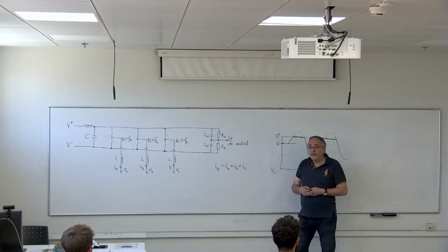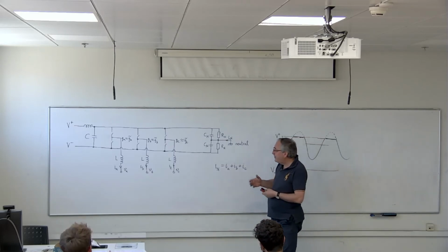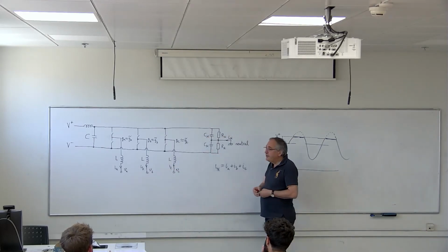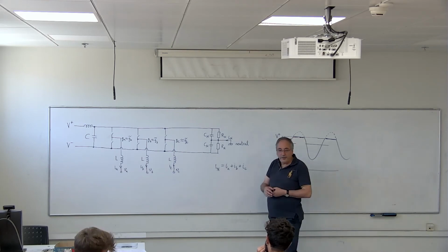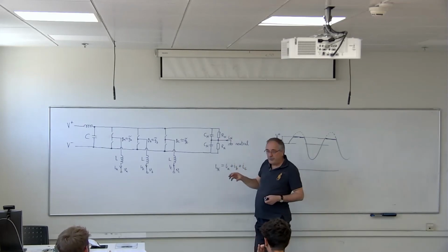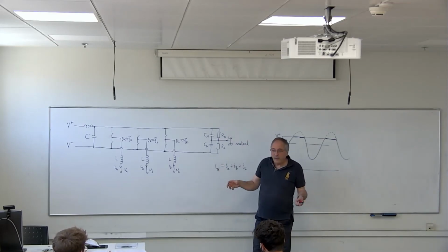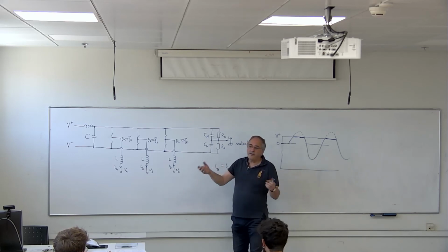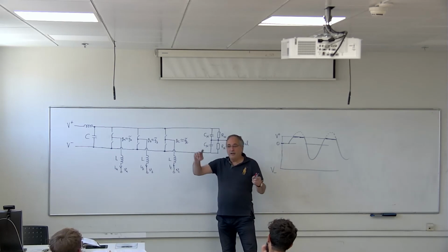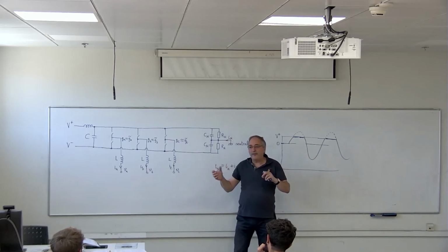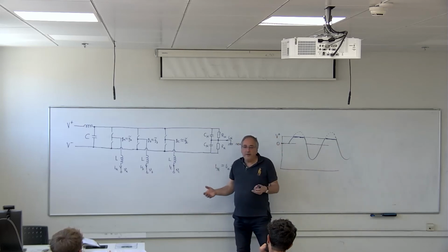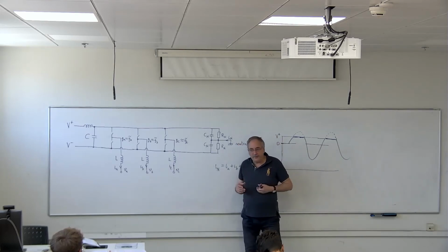So suppose you have this UPS, and it's connected, of course, to the 3 phases inside this hospital. But you know, in the hospital, most consumers are one-phase consumers. So in each socket, you have only one phase. Now, it's true that they distribute them in such a way that in one room it will be phase A, and in the next room it will be phase B, and then phase C. So they try to balance it. They try to have approximately equal load on the 3 phases, but this may not work out exactly.